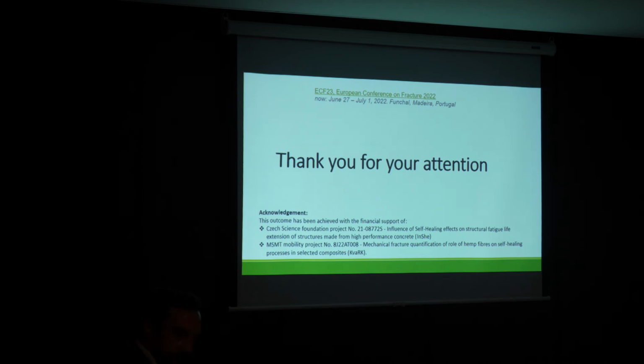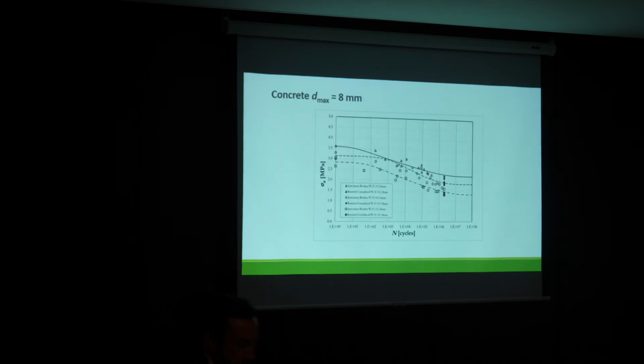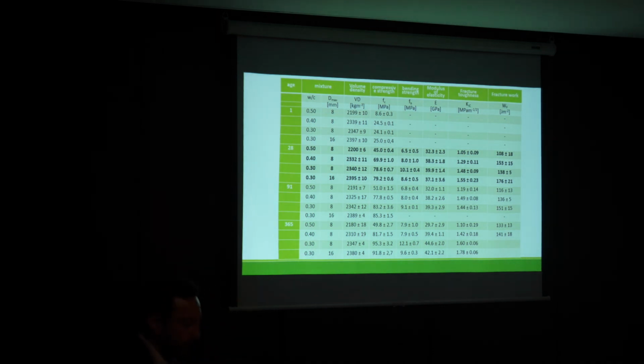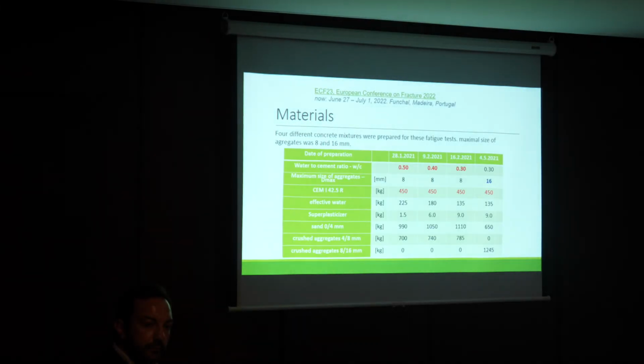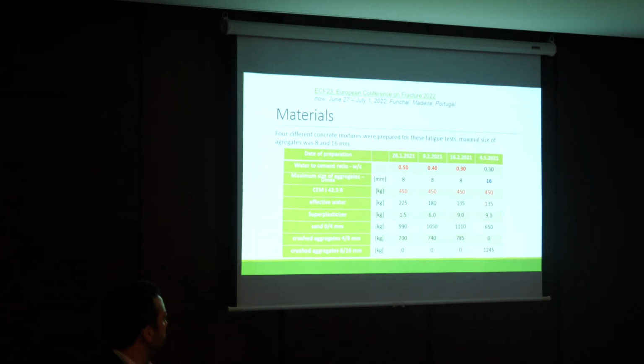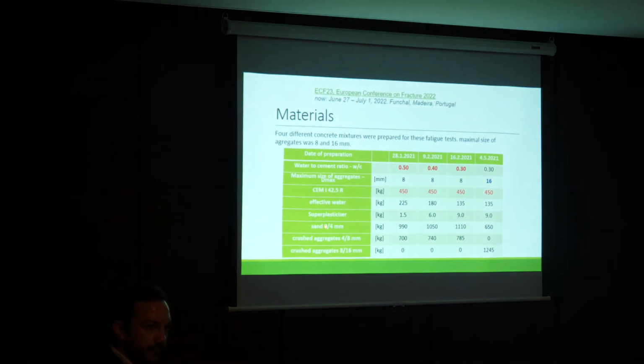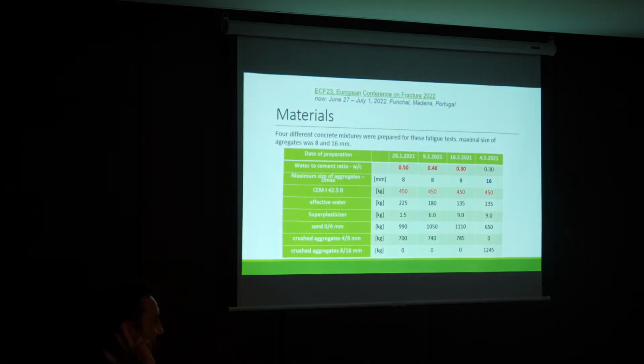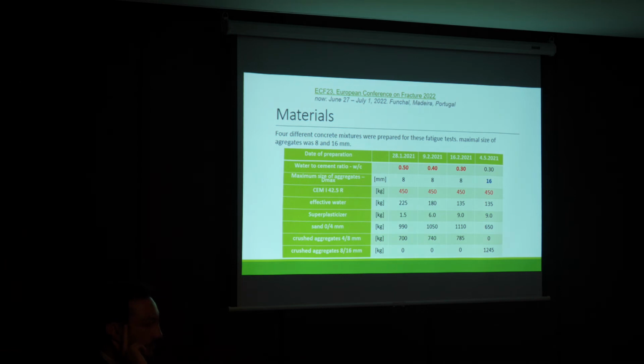When you reduce the water cement ratio, do you add something like adjuvants to the mix? Because you know at 0.3 it's really a dry concrete mixture. So yeah, okay, you mean if we add superplasticizer? Yes, it's increased. As I said, we replace the water with the superplasticizer.